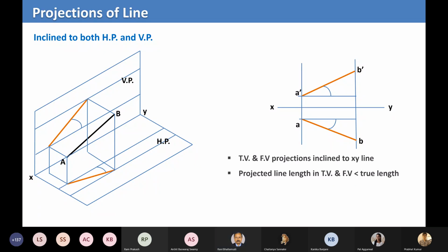Okay, fine. Now let's look carefully at the projections of this. What we said is that point A is defined, so we know exactly its distance from the XY plane in the front view and the top view. So you can mark the point in the drawing sheet. No problem. And let us say we told you the angle of the line AB, in the front view, its angle of inclination from the horizontal plane. Otherwise, the line will be like this only, right? So you can draw the line AB also.